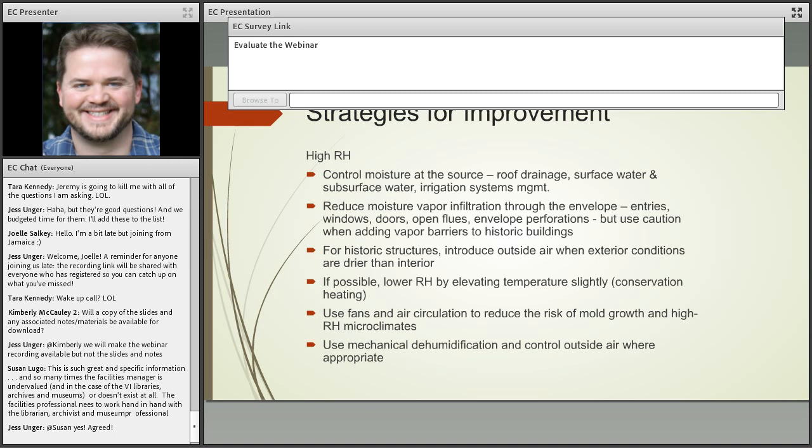So pressurization is still one of those areas that can vary in the application. If you have a particularly dirty or clean environment that you're either trying to keep out or trying to keep in, pressurization can still be designed. But especially for storage environments, it's about thinking less about positive pressurization and more about not letting unconditioned air into the space. Positive isn't necessarily required for that. We can work with neutral. Oftentimes we can get away with less outside air in that equation.